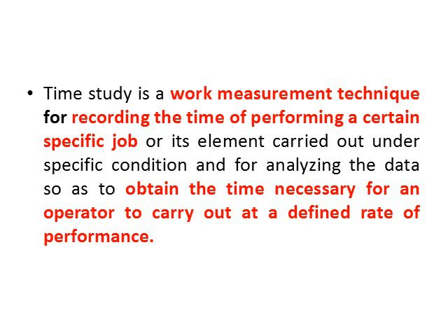Basically, through time study, we will record the time taken by each operator, and we will compare it with the standard time. So what is the objective of time study? We do time study for increasing the productivity, to determine the actual time taken for doing a job, and we will make a standard, and we will compare the time taken by each employee with the standard time we have already set.